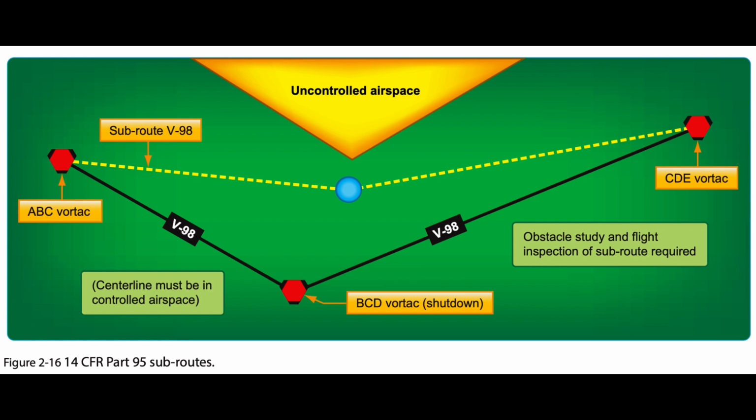Non-directional radio beacon, NDB, facilities may only be used where VOR/VORTAC coverage is inadequate and ATC requirements necessitate use of such navaids. Where operational necessity dictates, navaids may be used beyond their standard service volume, SSV, limits that define the reception limits of unrestricted navaids, which are usable for random/unpublished route navigation, provided that the routes can be given adequate frequency protection.